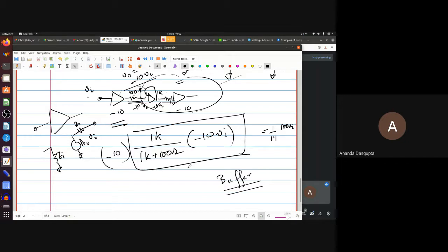Approximations are important and they are part and parcel of whatever you do in physics. The important thing is the approximation has to be controlled. You should know what kind of errors are involved there. So when you say high precision, it depends on what your application is. For some applications, the H parameter equivalent result is fine. For some others, it's not. Okay. If you want very high precision involving a transistor amplifier, maybe the H parameter equivalent will not be good enough. The H parameter equivalent would be a good enough starting point to give an indication of what the circuit will do. But if you wanted to know whether the output will be exactly 3.10 volts or 3.11 volts, you may have to resort to more precise modeling of the transistor.